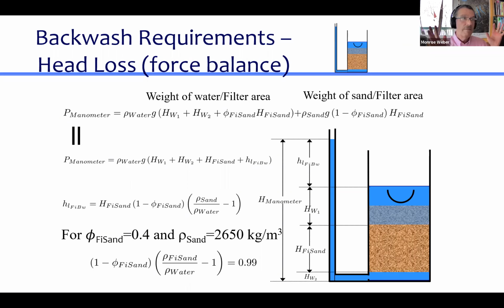And so, here's one very simple practical result. Our stacked rapid sand filters are very carefully designed, and they're designed for using silica sand. And if you, as a very clever engineer, said, I think it'd be more fun to use garnet in those crazy stacked rapid sand filters, and you replace the sand and took out the silica sand and put garnet in it, and then you tried to backwash it, it would be a complete fail. The filter hydraulics aren't capable of delivering enough pressure to backwash garnet.